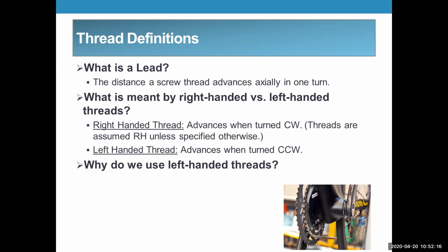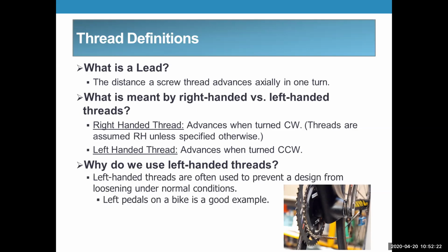Right, exactly. And of course, the bicycle on the left-hand side, the same thing, the left pedal. That is correct. Left pedals on the bike are usually left-hand threads because the action of you pedaling the bike, if it were a right-hand thread, would try to unthread it and spin it out. Going down the road with 1 foot on the ground and 1 foot on a pedal.